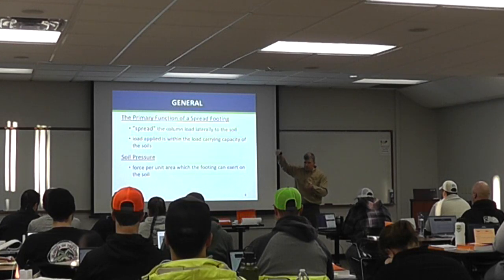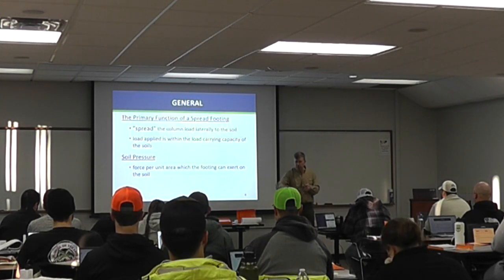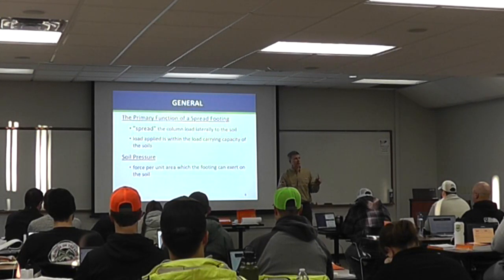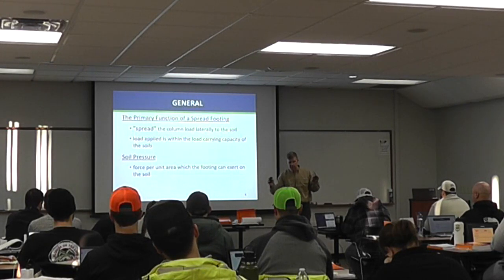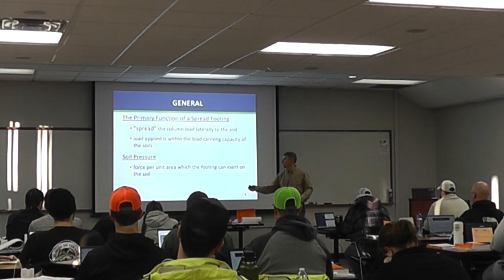And the weight of the soil that's behind the abutment is not only pushing laterally, it's also vertical load, so it's helping to balance. And so in bridge design, that's what the designer does. They balance where the stem is compared to how far back and how far in front it is.